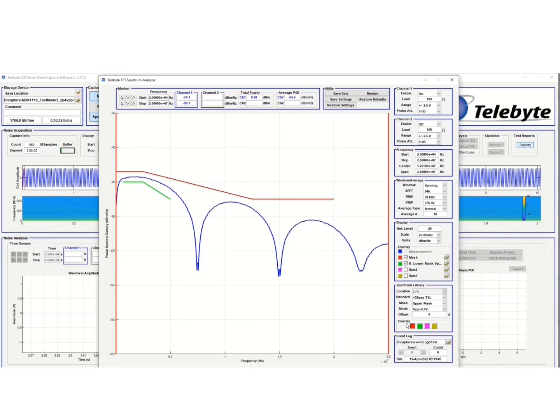So what we see here then is the signal is in blue, and the upper mask is the limit of the transmit power for the upper limit mask, and then the lower limit mask you can see is only defined out to 5 megahertz here, and it's the green line here. So the signal must stay within the mask limits, and it looks like it is just perfectly fine.